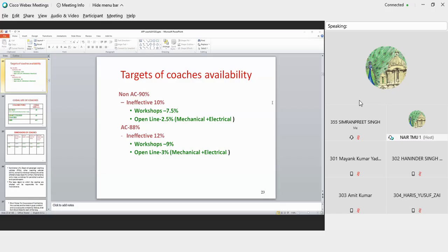Can a train be entirely solar power propelled? Does the surface area and current technology conversion efficiency allow it? The train cannot be 100% solar powered directly. Solar paneling, which we have tried to do now, is basically to take care of the light, fan, and the AC load. Yes, if you have a surface area, like at Bina, Indian Railways has set up a solar power plant generating 2.5 to 3 megawatt. That electricity gets connected to the catenary, and from the catenary you can take the power.